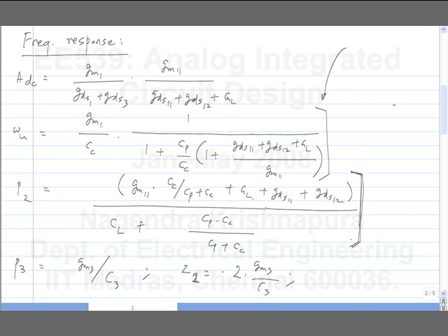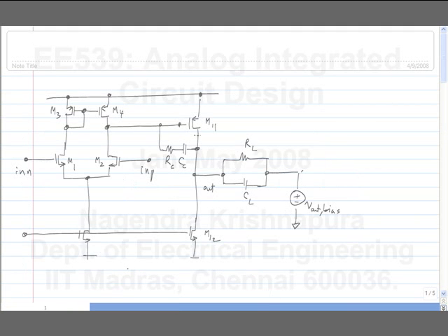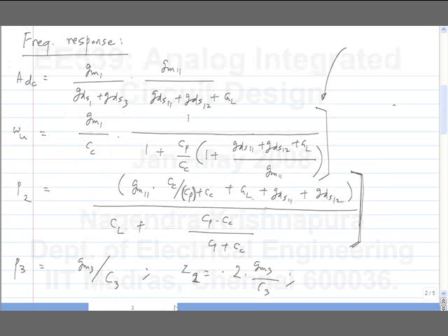Now, this parasitic capacitance Cp at the output of the first stage depends on the first stage itself, so it is proportional to the first stage width or the first stage scaling factor alpha. But it also has CGS12, which is fixed. I can scale this part, but I can't do anything about the CGS of this once I have chosen M11. So if I go on reducing Cc, Cp will reduce but not in the same proportion.